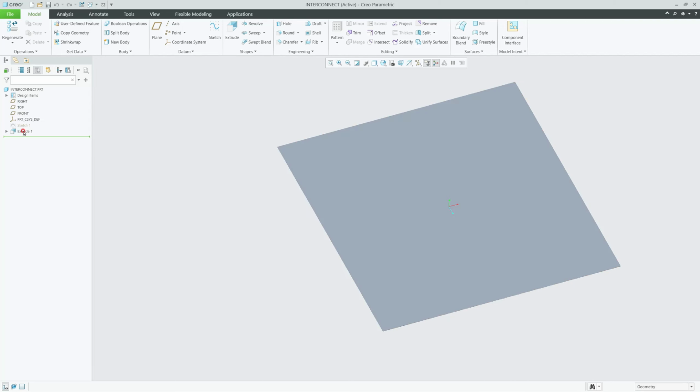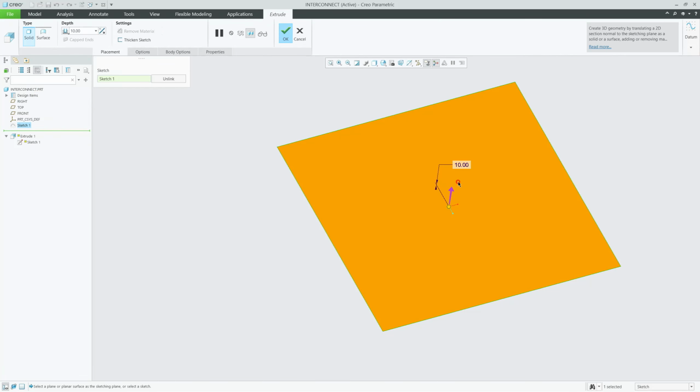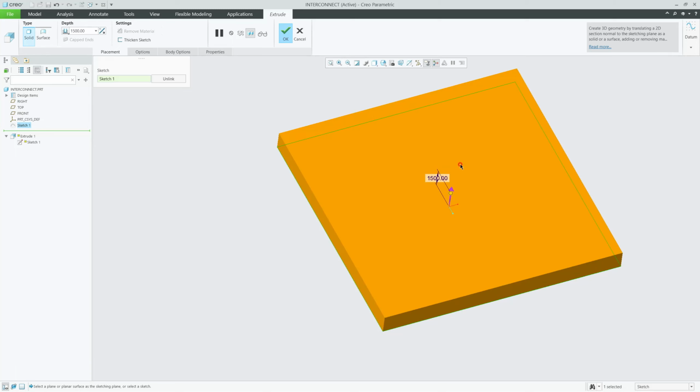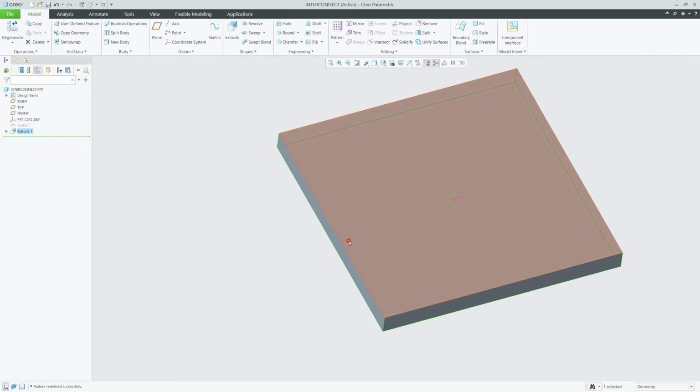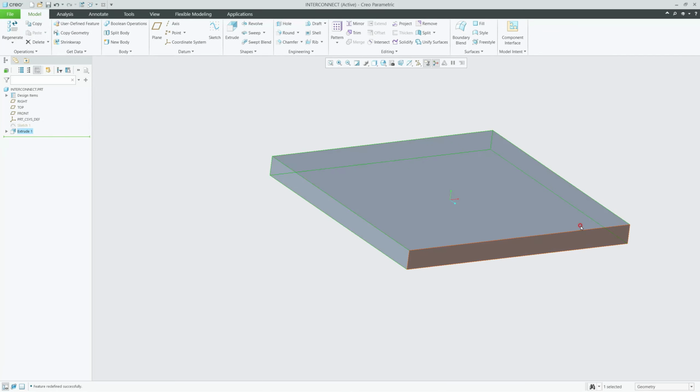The first thing that we should do is modify the interconnect height. That is, we will take it to 1500 microns, that's 1.5 mm. And now from here we will extrude the geometries, exclude the geometries that we don't need, that are corresponding to the manifold, and that's the channels of 1 mm by 1 mm. So we'll take, for example, the top surface, right surface, sorry, front, and sketch.